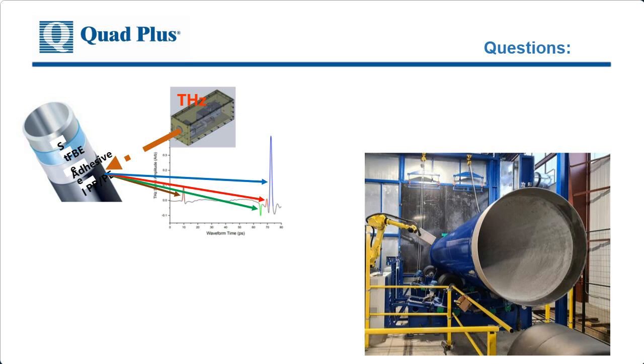What is the measurement spot size? That's an interesting question. We nominally say it's about 2 millimeters. In reality, it varies with the frequency content of the pulse. So sort of a maximum of about 5 millimeters and a minimum of 100 microns, but most of the energy is in about a circle.